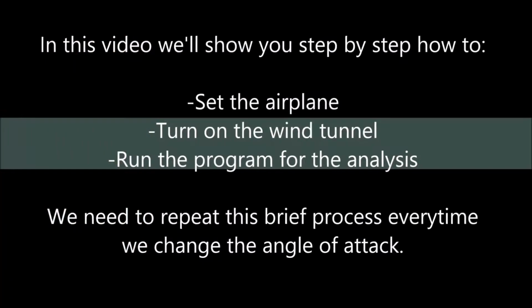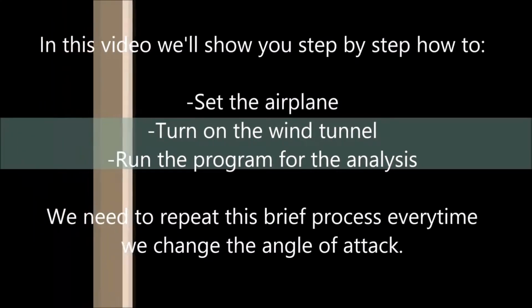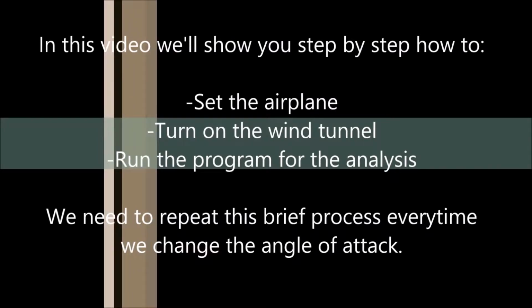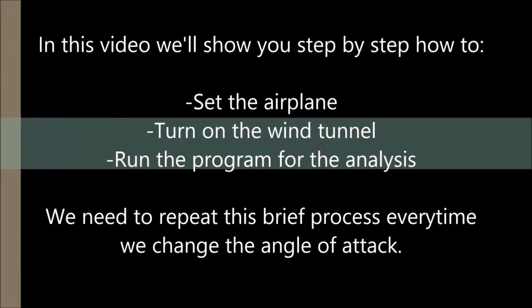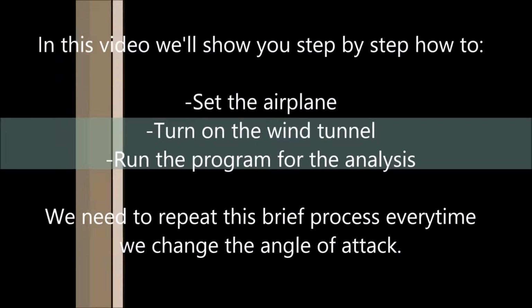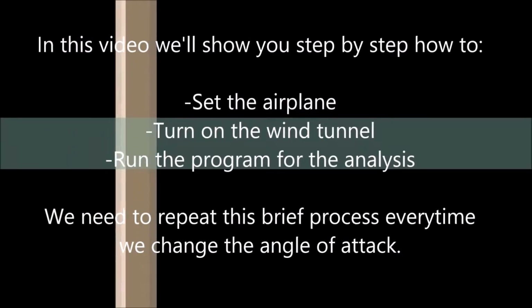And once we have the wind tunnel on, it's time to run the program on the computer for the lift, drag and pitch analysis. We need to repeat this brief process every time we change the angle of attack.